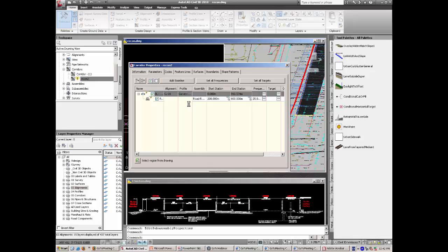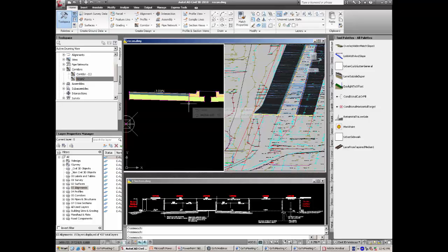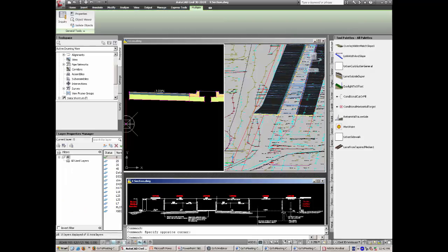So what we're hoping to see now on the right hand side in the shaded view is the main carriageway attached to our drawing and stretched onto our median. And it's worked properly. You can see how it's tapering just on the end closest to us. That's where the right hand turn lane starts. So we've now basically on our bottom screen where the cross section is, we have built everything across here.